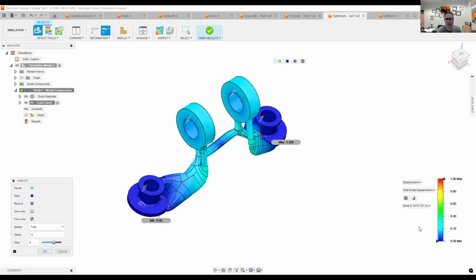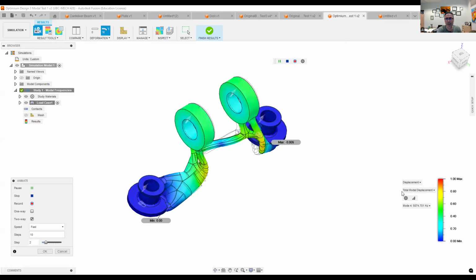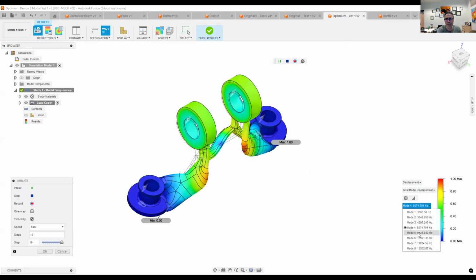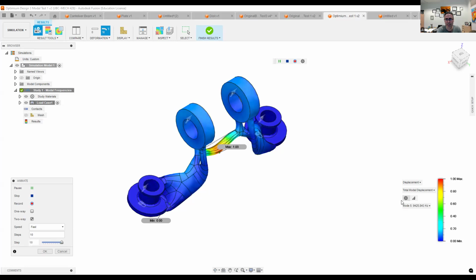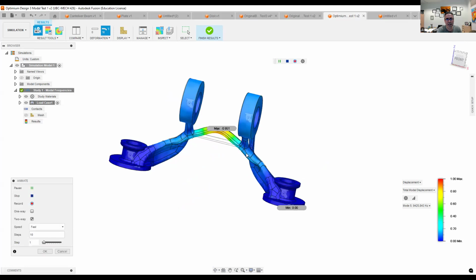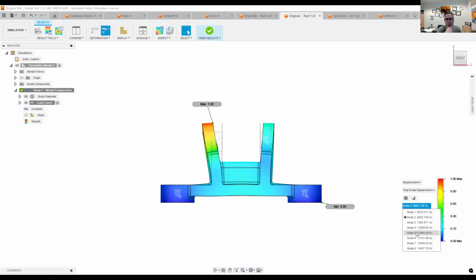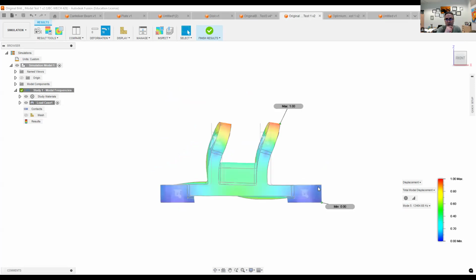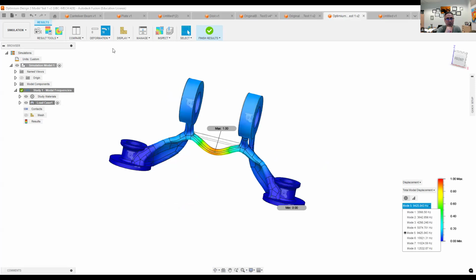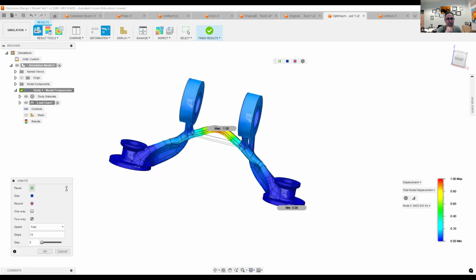And the fourth mode, now the mode shapes are a little bit different maybe, and that's because of the pattern. For example, the fifth mode on this one, as you see, only the middle part, because it has a low stiffness, is being excited. But on this one, we don't have that fifth mode. It's actually a different mode shape, different frequency. Again, that's because in the middle we have lower stiffness.